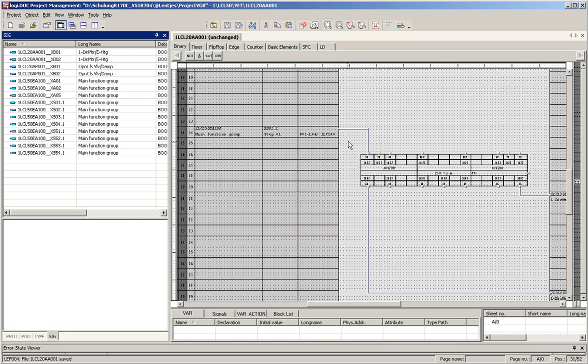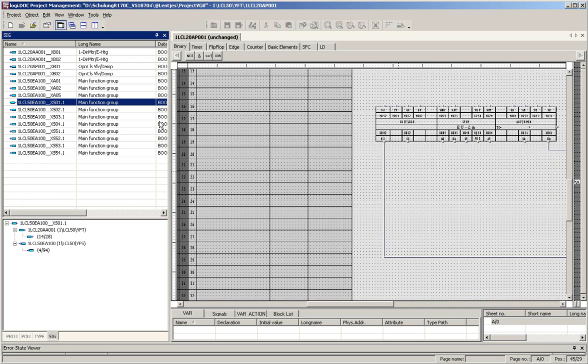And when this input is saved, then you will directly see that the system automatically builds up the cross-reference. Therefore I can see where this signal is used, and I can directly jump from this motor back to the sequence. This is the cross-reference. You see, we have one point where the signal is generated. This is inside of the sequence, and we have the signal where this signal is used. Now I open the motor and will do this again. The signal is dragged. Now it is connected.